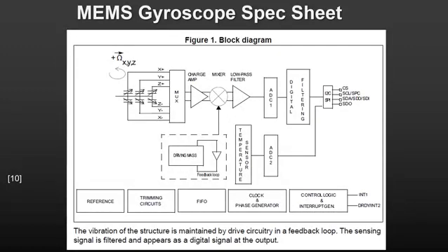The block diagram for the drive circuitry should look familiar to you by now. We need a charge amplifier to convert the charge on the 3 capacitance circuits, one each for rotation about the x, y, and z axes, into voltages. Because the signals are sinusoidal, we feed them into a low-pass filter and then an ADC to get an angular velocity readout. The signal requires some post-digital filtering so that the output to the I2C or SPI interface is stable.